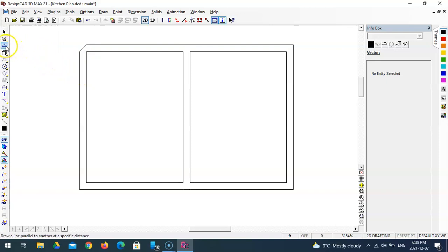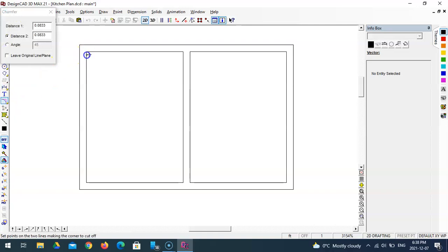Okay, let's now see what we can do for the inside chamfer before we decide. Usually we don't use the same chamfer because then this just becomes a bigger space. So I'm actually liking the 1 inch for the inside. So let's use the 1 inch for the inside. I'm going to Control Z those two, or Edit Undo. And I'll go back to here and I'll just do the inside one more time.